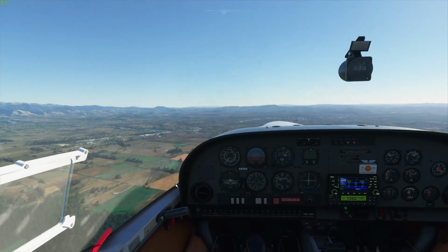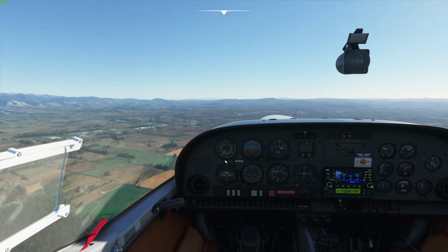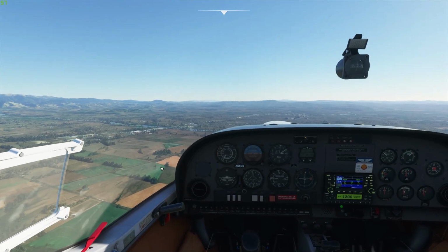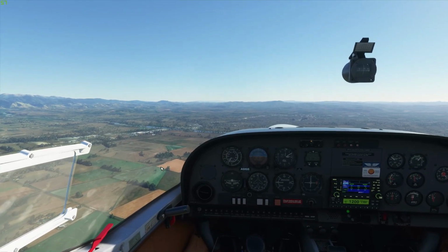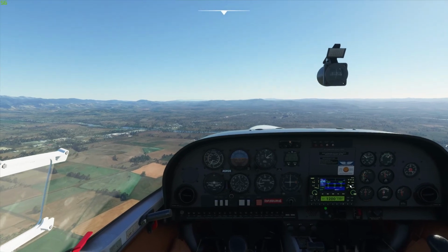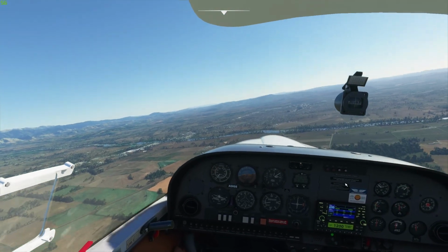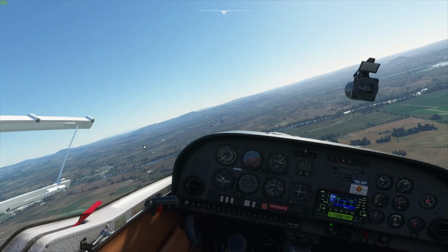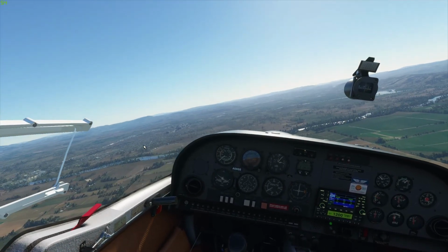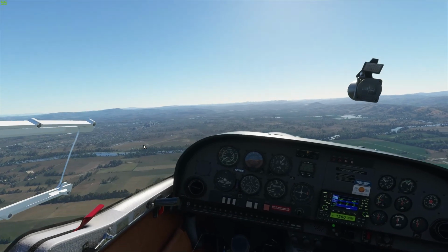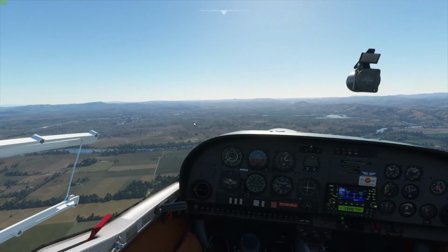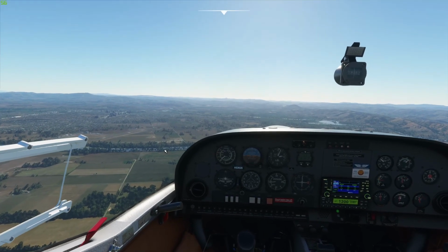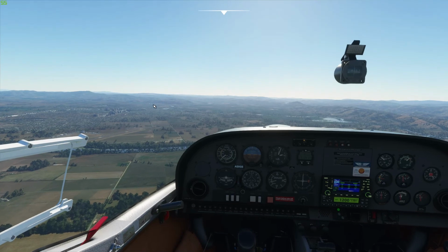Okay, so we've learnt that, and it's still just wandering around, and it's pretty much back at 96 knots and coming back to level flight. I haven't touched the stick since that first 10 knot change, so that's good news. We can see that it's a very stable aircraft, ideal for these conditions. There's the airfield there. So that's about all we'll go into with the stability and handling for today. And we'll continue for a downwind here and re-land on runway 24.